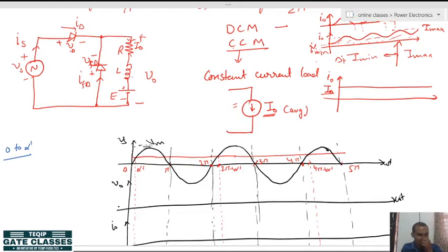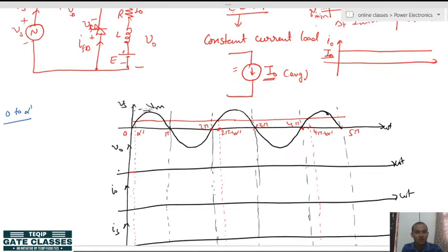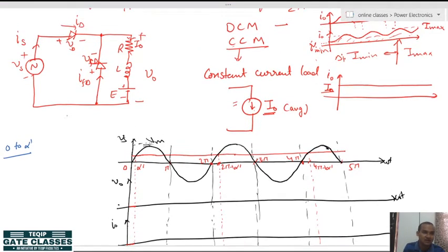E. All right. So, both diodes are reverse biased. So, the circuit will not be in working condition. So hence the output voltage will be 0, and hence ultimately the output current will also be 0. Output voltage 0 and load current will also be 0, because you can draw its modified circuit, you will get like this, like this. So everything is disconnected.